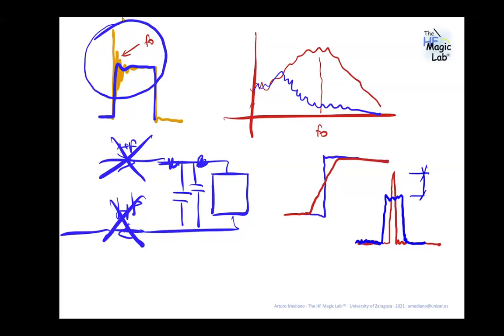Any advice to reduce bulk current induction for twisted pair, but a 25-meter long truck harnesses? I've got that right. No, probably the only possibility is to filter, I think. Filtering is what I think. I consider that you cannot shield, no? If not, shielding is another solution.